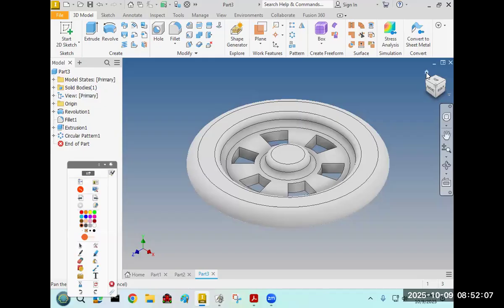All right, are you guys stuck on this one? You need a circular or a center point arc. Underneath arc, they drop down for arc, and a type of arc, center point. First click is on the center of the field, center of everything. Second click is on one of the 30-degree lines.